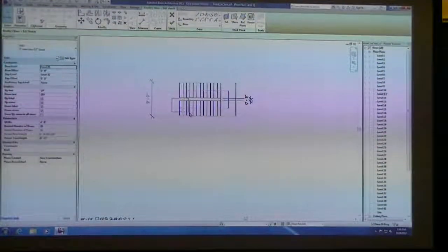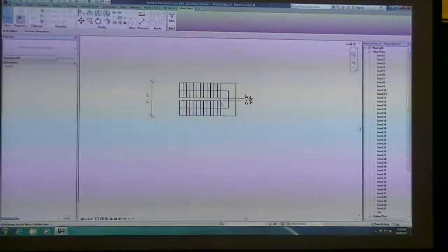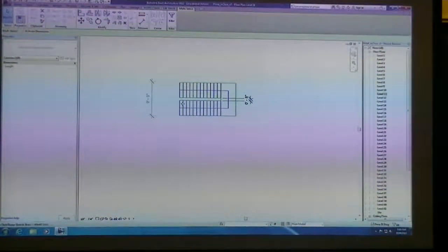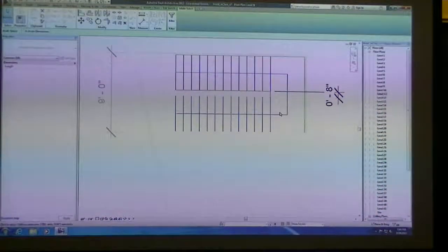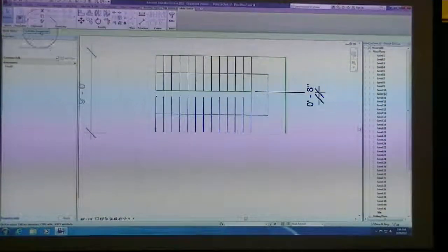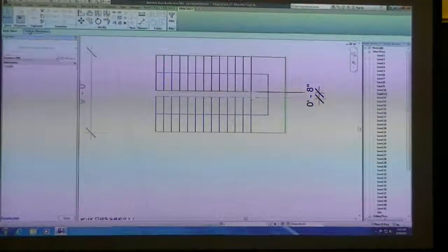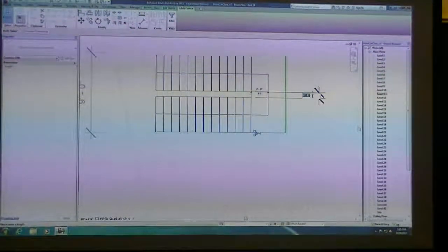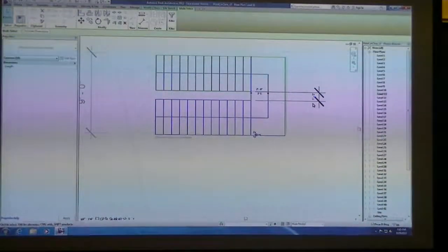And then if you window over one whole stair run, so you're selecting all the green lines and the black lines, and there's like a blue line in there as well. There's a little button that should show up to the top left where it says multi-select in your options bar. Click on activate dimensions, and then you're able to select that dimension and change it to, I could make it 1 foot.